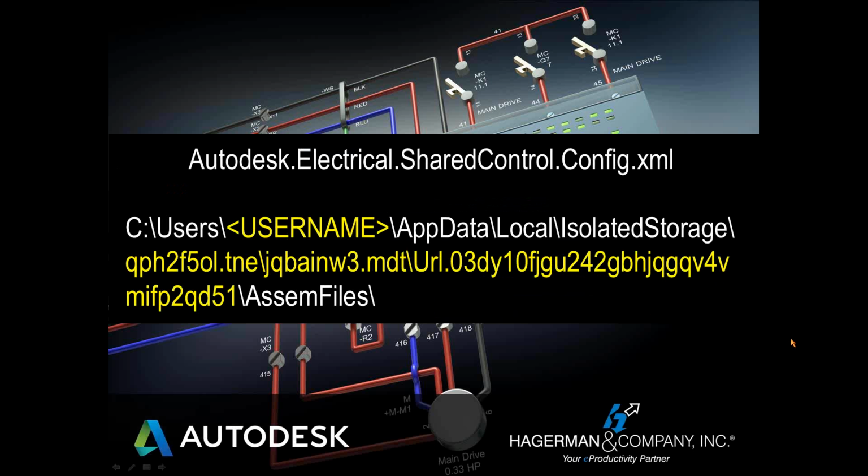Now I'm going to pull up a little screenshot here for you. There's the name of the file that's going to control this, and there's the location it's going to be on your computer. So you may want to write this down as much as possible, but what's in yellow is going to vary from computer to computer. For instance, username, of course, is going to be whoever logs in. So it's going to be under the users, then username, and then go into this app data. The other folders here are automatically generated by AutoCAD, and it's going to vary from computer to computer. But they should be the only files there. Whatever it generates, you go through there and find assembly files, and you'll find this file.